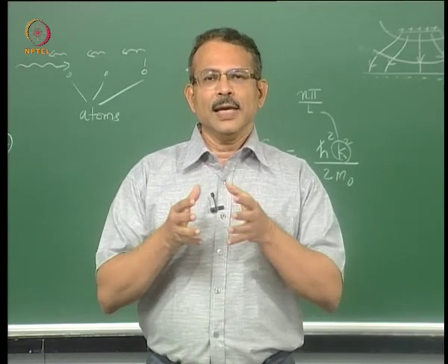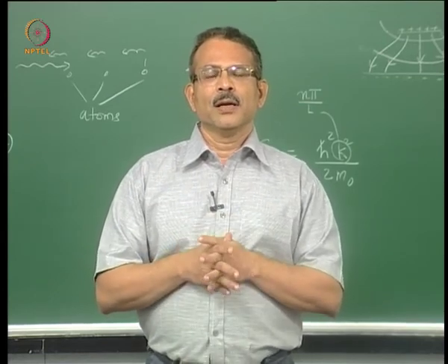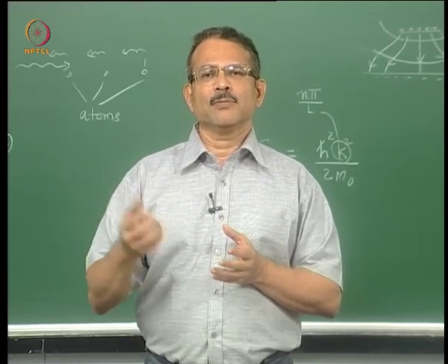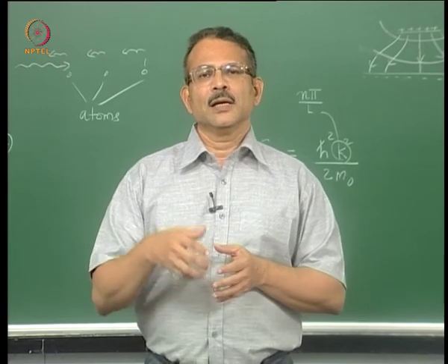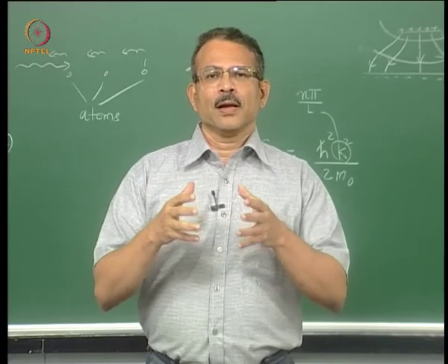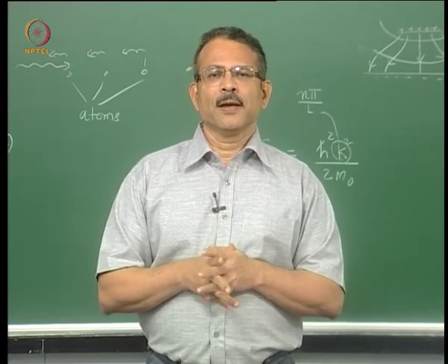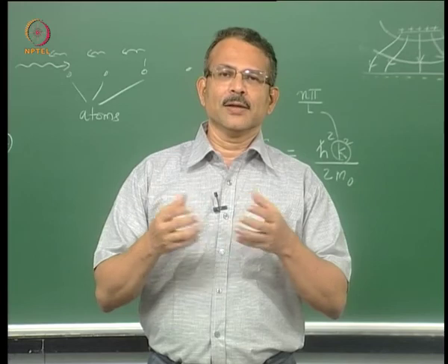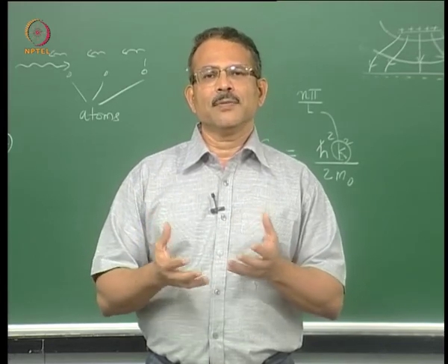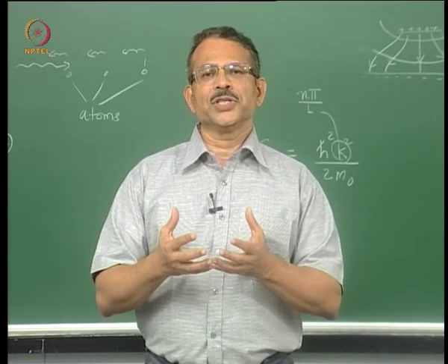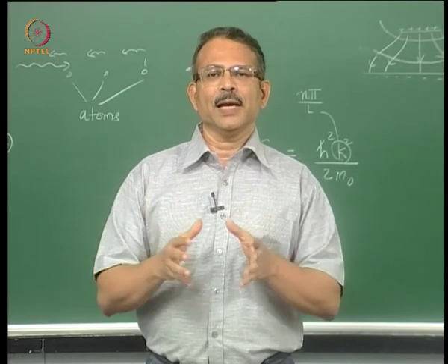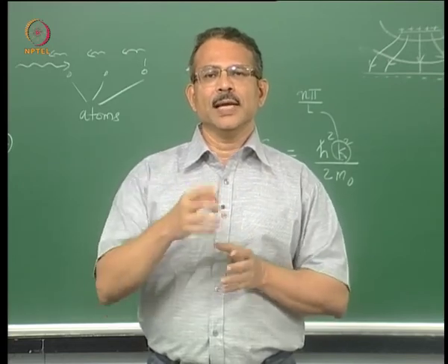On the other hand, the E-k diagram helps you to derive the velocity, mass, and momentum of the electron, which are referred to as group velocity, effective mass, and crystal momentum. This information is important because the interaction of electrons with other carriers, impurities, phonons, photons, etc. are governed by the laws of conservation of energy and crystal momentum. So one can study the behavior of these interactions based on the E-k diagram.